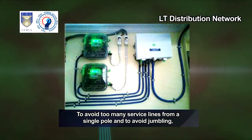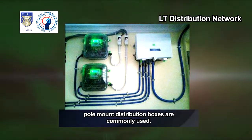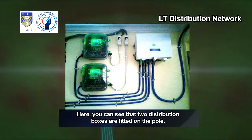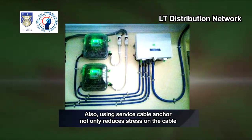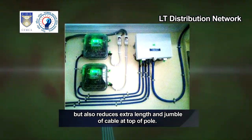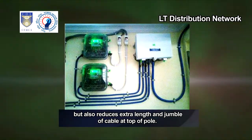To avoid many service lines from a single pole and to avoid jumbling, pole mount distribution boxes are commonly used. Here you can see that 2 distribution boxes are fitted on the pole. Also, using service cable anchor not only reduces stress on the cable but also reduces extra length and jumble of cable at top of pole.